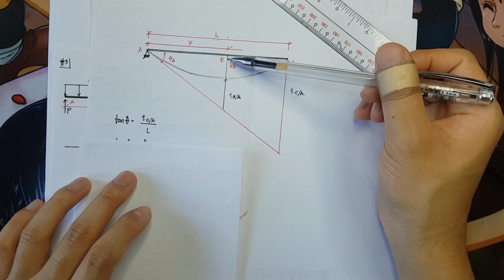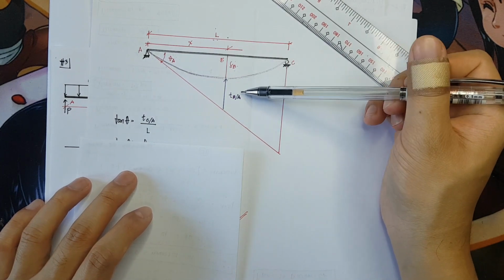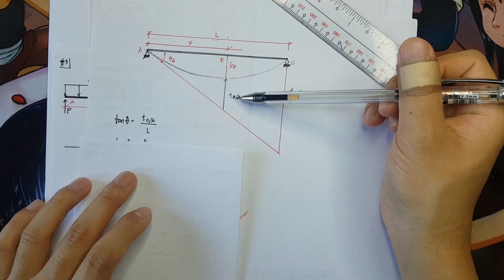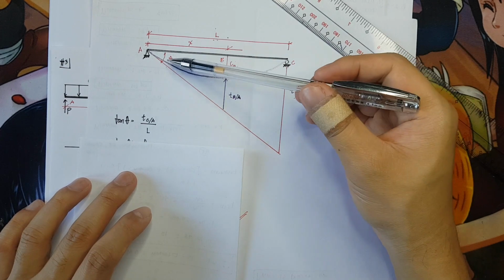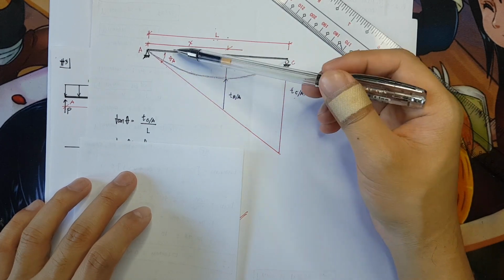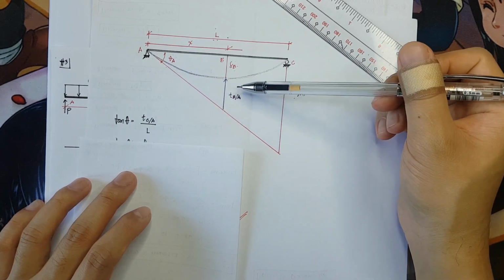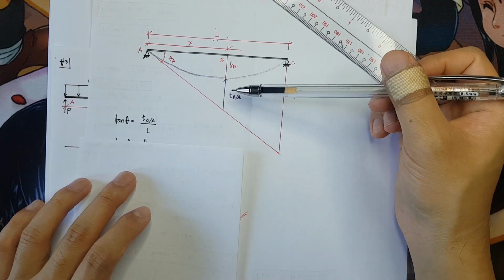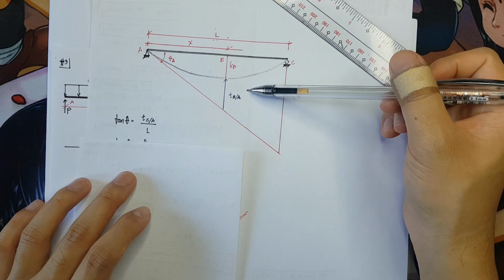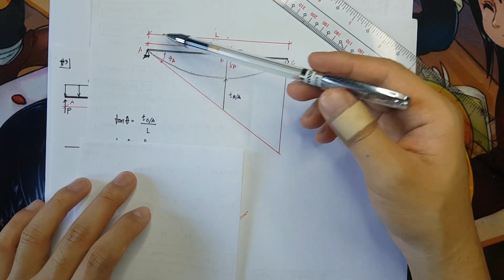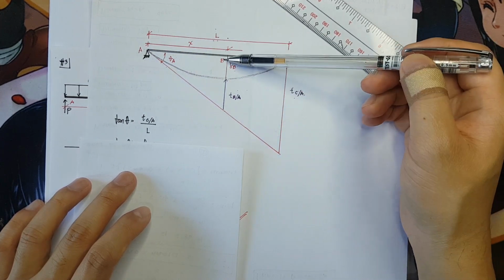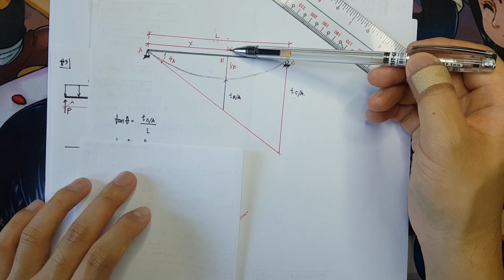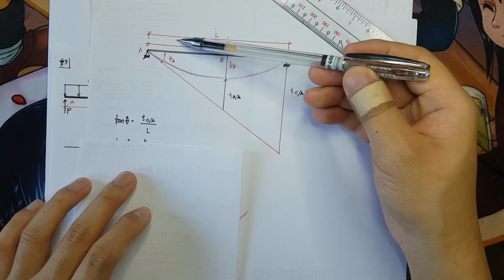We have the deformation at B, the tangential deviation from B relative to A, and the unknown theta A. The tangential deviation can be solved via the area evaluated from point B to point A times the lever arm. But theta A is unknown.